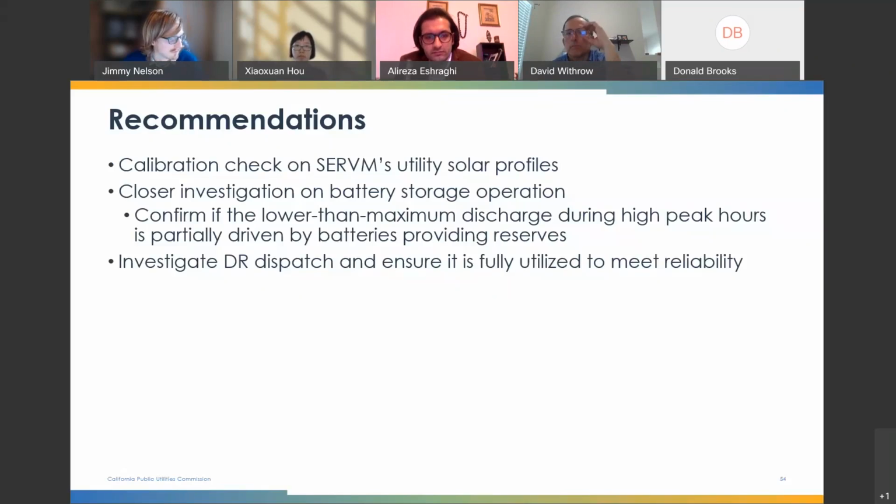So I wouldn't say that that would explain the commitment questions on the combined cycle. Just to offer a little bit of flavor on what changes we made to the commitment to reflect more flexibility on the combined cycles. Inside the commitment window, we use a dynamic programming algorithm to determine our commitment. Part of that algorithm steps up the commitment, so it looks at incremental commitment decisions relative to a base decision.